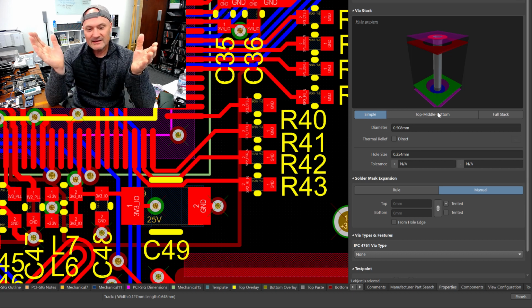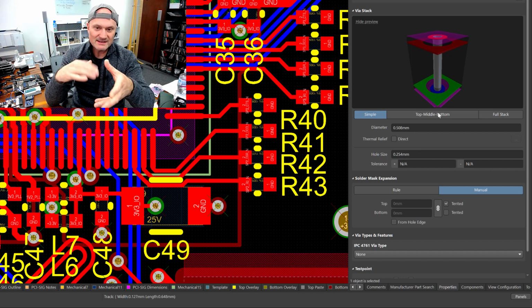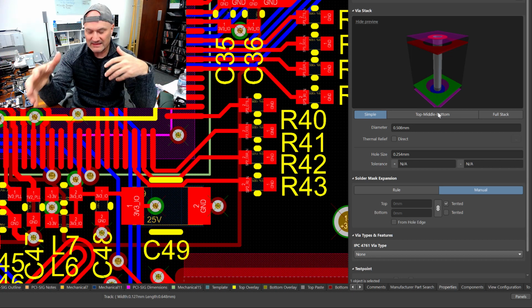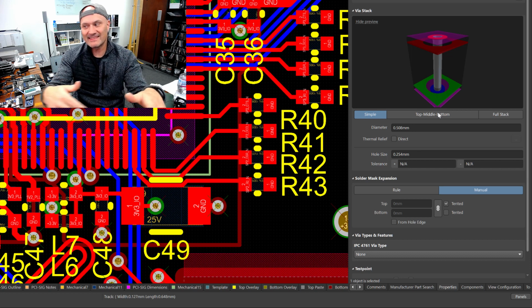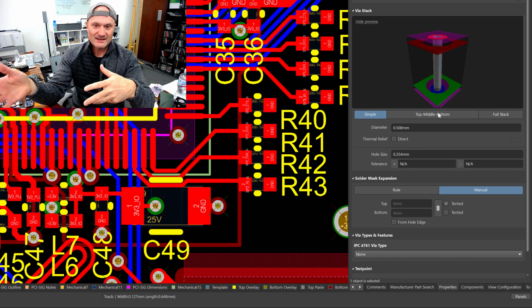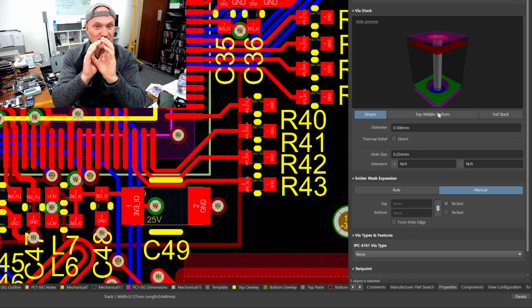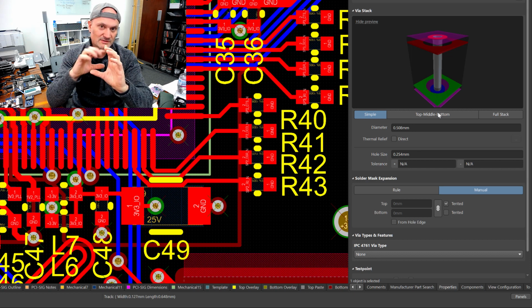So in just a bit of history, in some of those other tools, the reason they do things in a pad stack was it was the only way that the developers of those tools at that time, with the constraints systems and their paradigms, it was the only easy way to make it so you could predefine how much clearance from copper pours and plane layers you would have, for example.